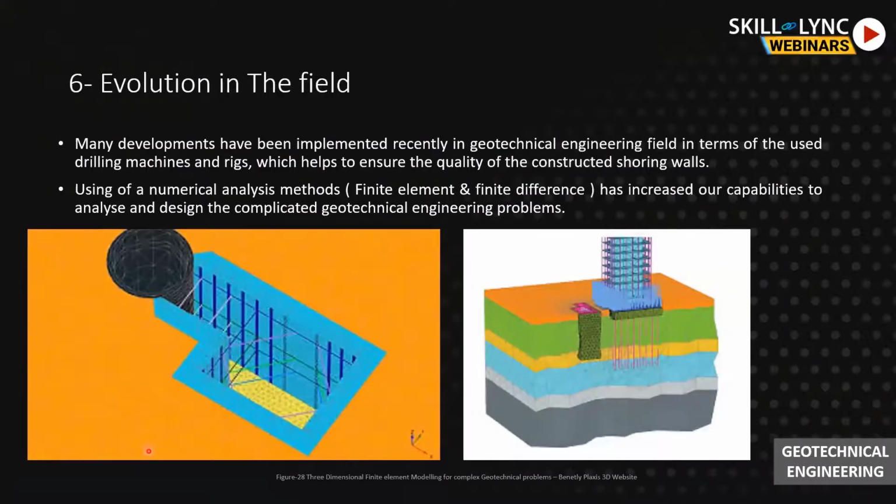Yeah, so evaluation in the field. Currently, Plaxis has launched, some years ago, the Plaxis 3D. This Plaxis 3D software is amazing. We can use it for any complicated project. As you see here, we have an existing circular shaft, and we have some excavation around the shaft. So we can model all of this actually. And if we have a high water level, we can do the seepage analysis. We can check exactly what is the displacement outside our shoring system. Here also we have another case. We have some deep excavation beside an existing tower resting on pile foundation. So 3D modeling and finite element method modeling in shoring design will be very useful for any project, and in the coming years will be used.